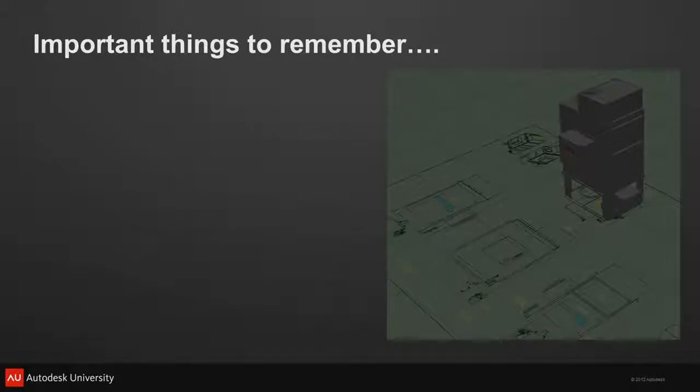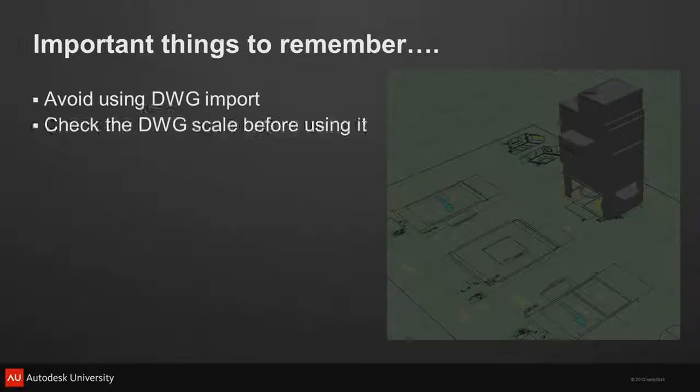Let's go through here. We're going to kind of run things down here. Important things to remember. Avoid using the DWG import workflow. In fact, let me put that stronger. Don't use it. It's one of those things that looked really cool. It demos great, right? And like I said, I used to be an AE. I'd show that stuff all day long. It demos really cool. But just because you can doesn't mean you should. It's just not a good thing.